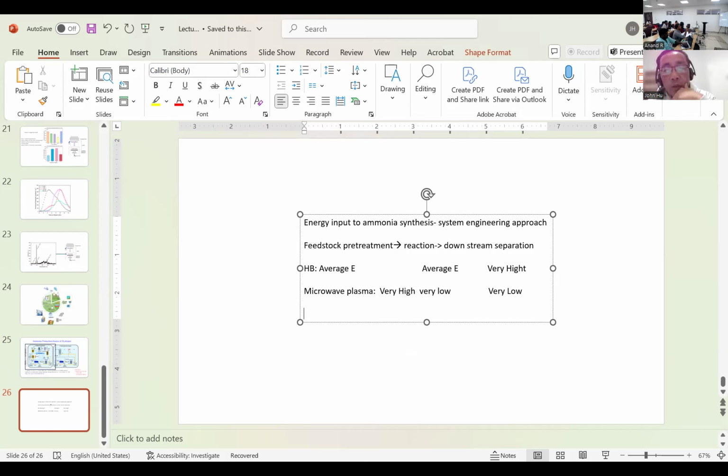Yeah, because by the way, microwave plasma, that's a process. Downstream separation, you do not use the plasma anymore because you are using the adsorption technology. Downstream separation has nothing to do with the microwave plasma. Microwave plasma just enables low pressure operation so that you don't have to use high pressure cryogenic. Downstream separation is just simple. You can use a conventional low pressure adsorption. You follow me?